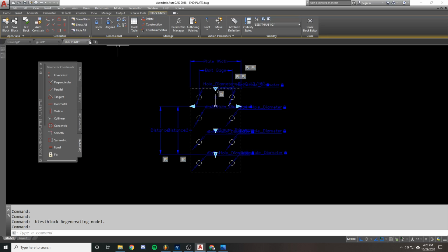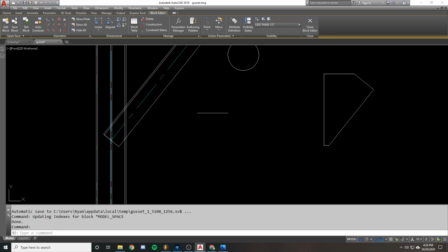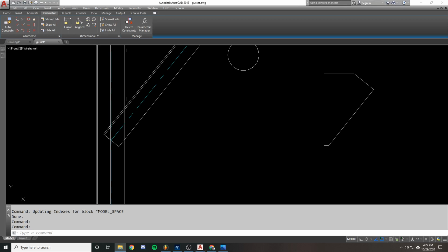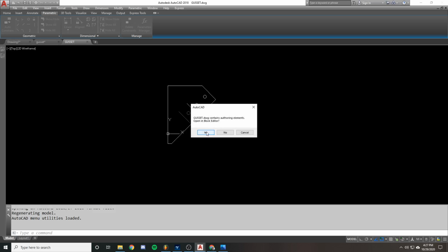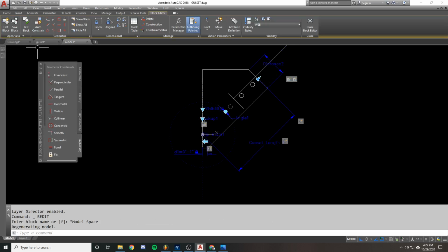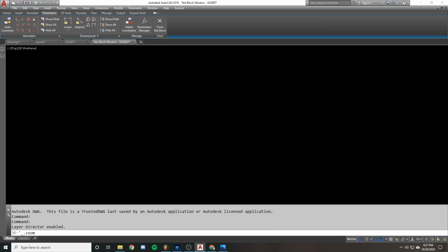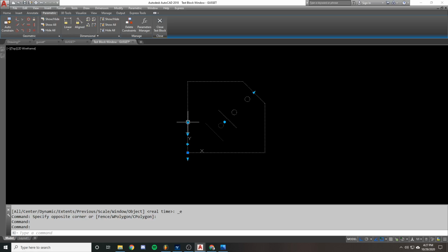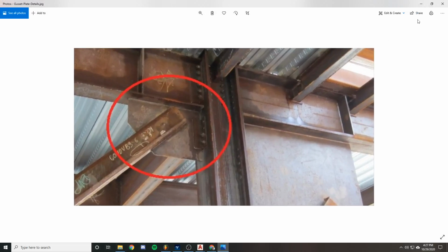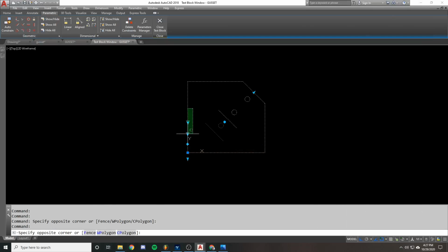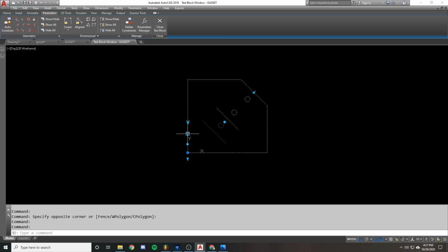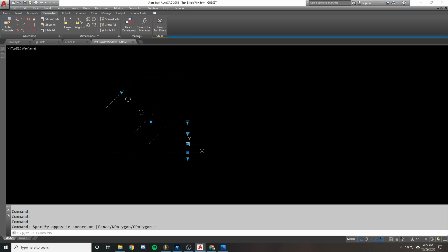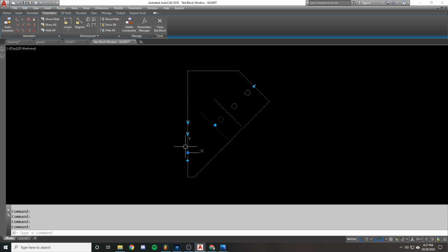That's the magic. And oh, look, and it turns out I'm going to show you real quick that I do actually have my good gusset plate. This is the finalized gusset plate, and this one actually does work. I'll test it. It's got some different variations of types of plates. This plate here is the one you saw in this picture. Just this one here is just upside down, and you can change the size of whatever the width of the member needs to be. It's got a mirror command, so I can mirror this around on all of these.